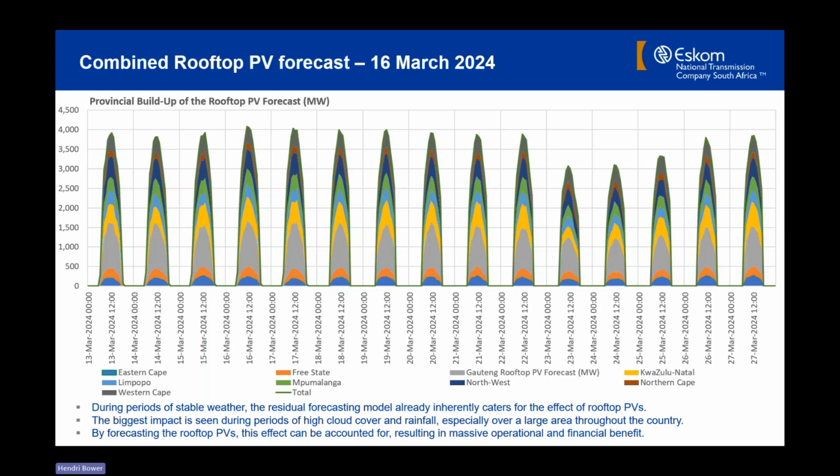And that's when there's quite a big peak in the morning. So that rate from the night minimum to the morning peak is still the steepest. But at this stage, the generators and generation can still easily cover that rate of change. Which means that the PV still needs to grow quite a bit for the rate at evening peak pickup to be at the same level, which means that generation will still be able to cater for that peak. So at this stage, it's not there yet where it's causing any problems, but I'm saying it with a big yet.